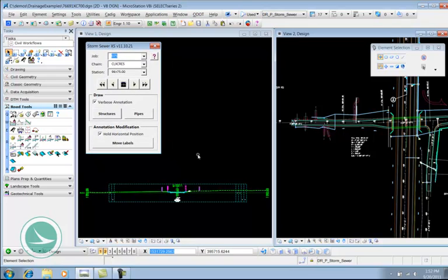And over here on view 1, it should have windowed in on the first section. So it's found the sections that are in the file, it's automatically gone to the chain that was used to create those, and I'm on my first section. And I've got the standard first, last, next, previous, and reset buttons for the cross-section navigation that you're used to seeing in GeoPack. Now these are a Visual Basic version of those, so the buttons are a little sluggish, so you can't quite click them as fast as the GeoPack navigator, but the function's the same.